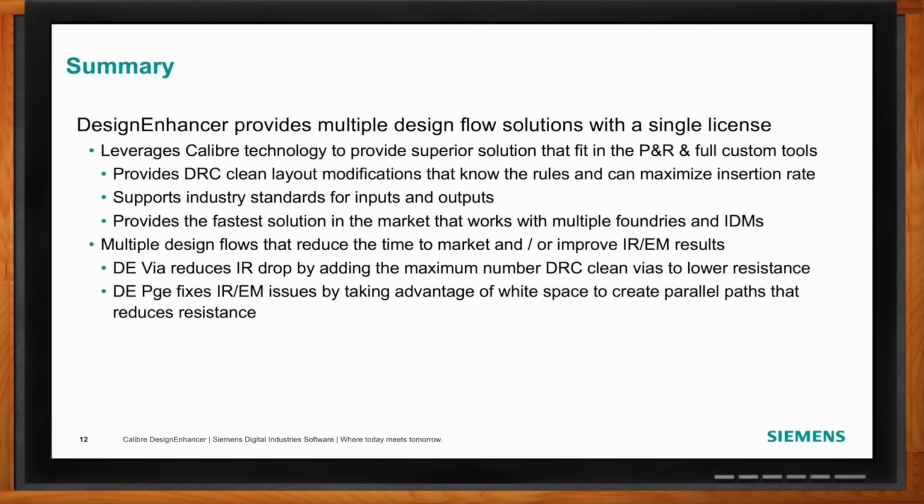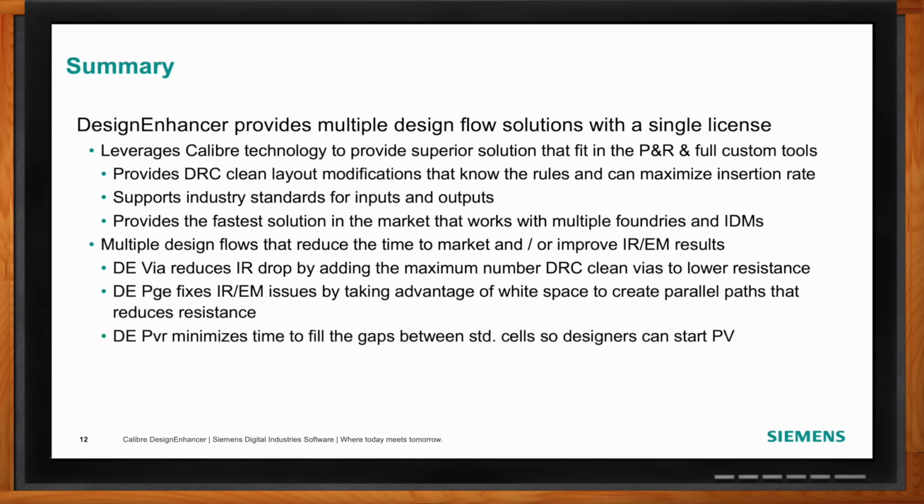But if you're doing a large SoC design and you are finding that your time to insert decap and filler cells is long, and even if, as some technologies require, M0 and cut M0 fill shapes have to be added, we support all of those different flows across the technologies. And so DesignEnhancer PVR is really focused on helping you reduce your runtime and get your designs to market sooner.